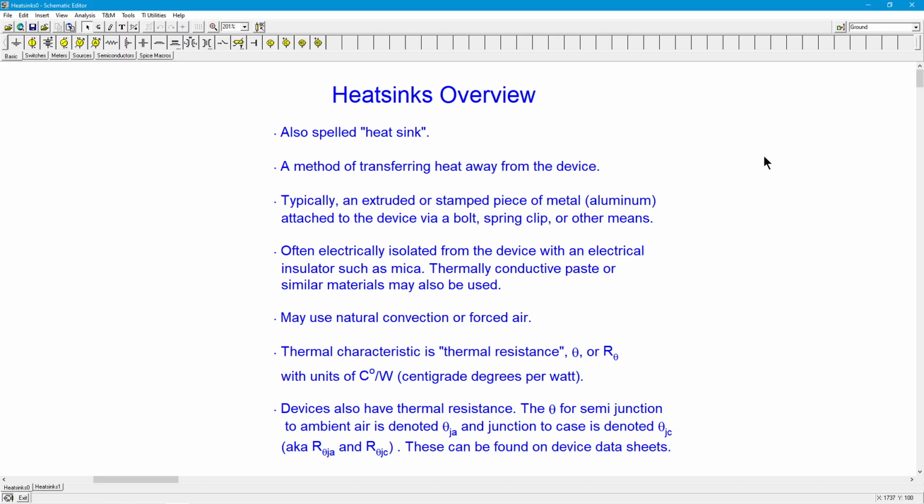Like I just said, with the TO3 case, the collector is the case. In other words, the case is electrically live. The collector on your power transistor might be sitting at 75 volts. In our little example, it was only sitting at 10, but a big power amplifier could easily be 75 volts or more.